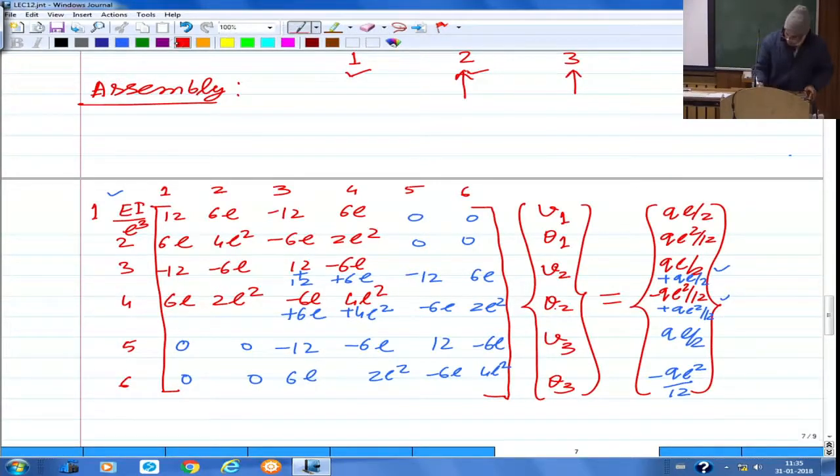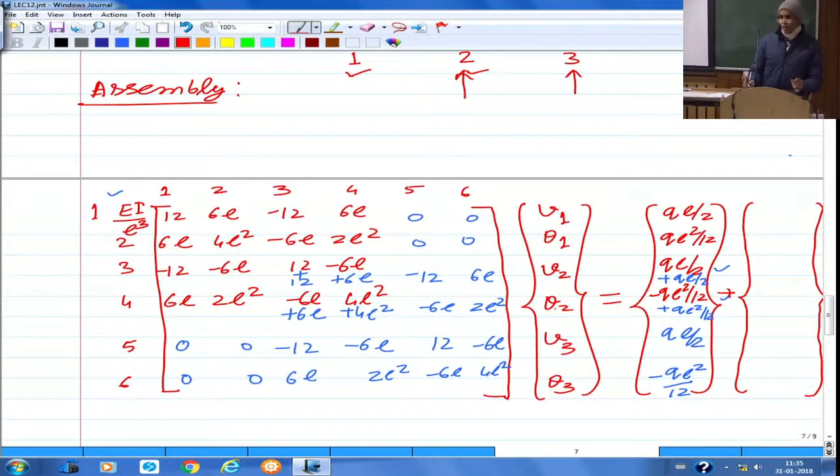So you have the first element. Now let us put the superscript to differentiate between different elements. So we had for the first element shear force S1 1 and bending moment M1 1, and then the third and fourth terms are S2 1 and M2 1. These are the contributions from the first element.